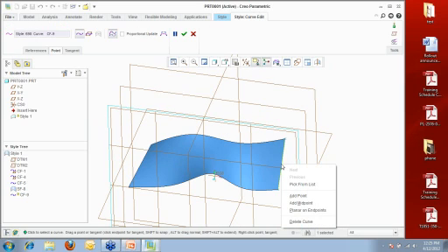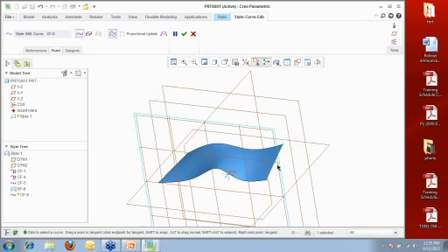I'll say edit the curve. I'm going to right-click, and here are the edits that you have. So for those of you that ever put a curve through points and have ever used the curve through points and the tweak and the tangency ideas, this is kind of what this is. And I'll show you this here in just a second, okay? Some of the tangency ideas. But what I'm going to say is I want to add a midpoint. Okay, there's my midpoint.